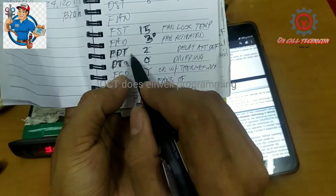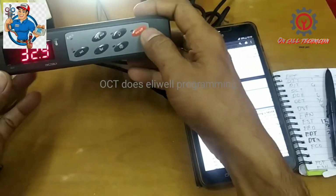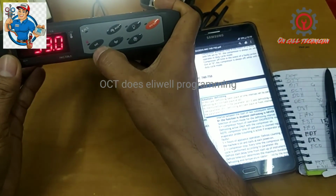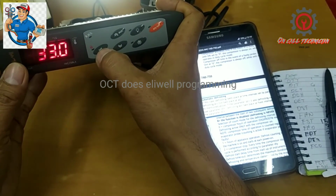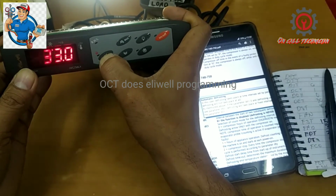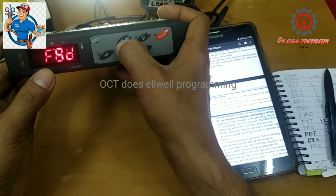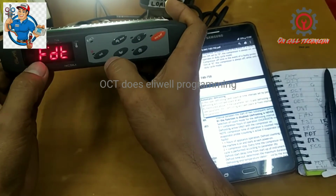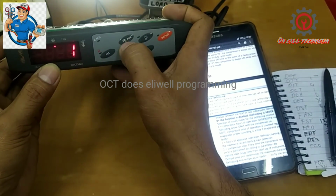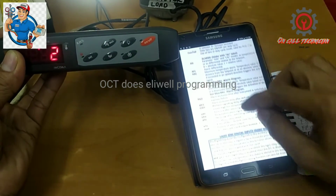Okay, for the FDT, delay after defrost, we can put 2 minutes or 1 minute to allow the drip water to go to the drain pan. So once again, let's enter the programming mode, and let's proceed to the fan. FSD is done, FAD is done, and FDT, this is the delay after defrost. So we're going to set a value of 2 minutes.